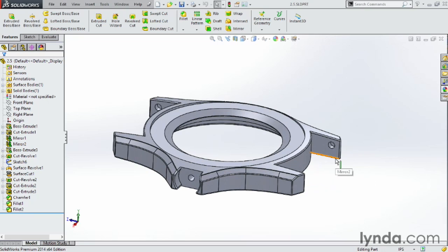The history bar is kind of a sneaky thing in SolidWorks. There's nothing really that shows what it is or where it is. So you have to remember, it's this little blue line down here. So if I click on this blue line, which is the very bottom of the feature tree, notice as soon as I mouse over that line, it turns into a little hand.